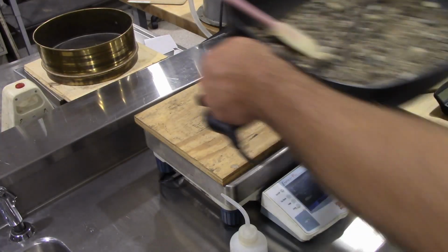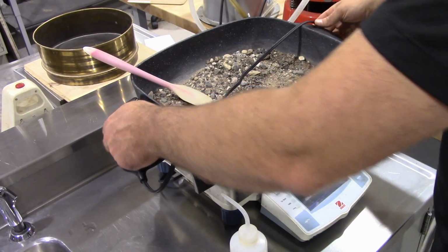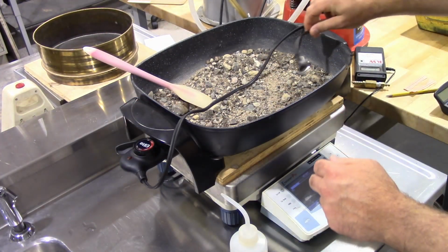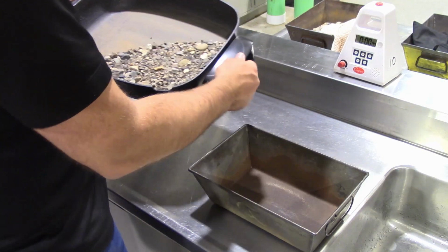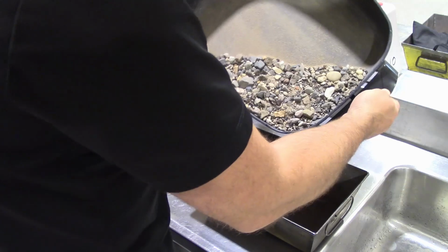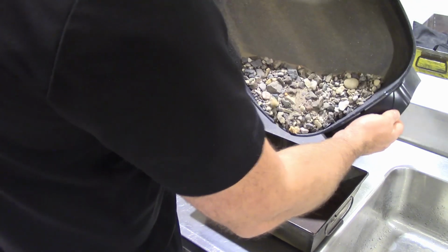If an oven is used to obtain constant weight, 20 to 30 minutes should elapse between these measurements. If the two weights are within 0.10% of each other, the material is considered to have reached constant weight.